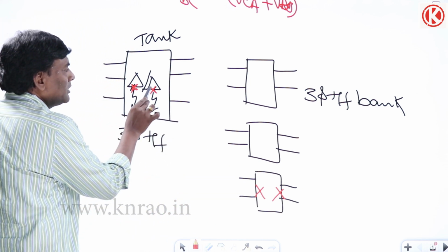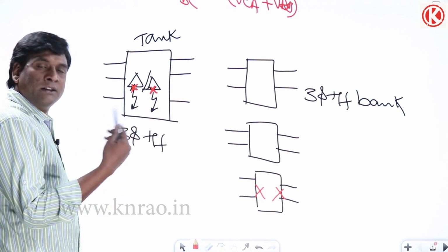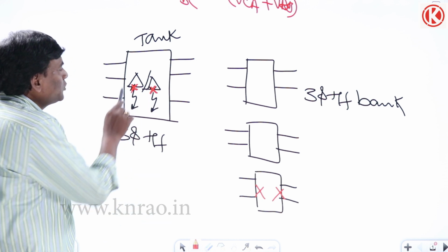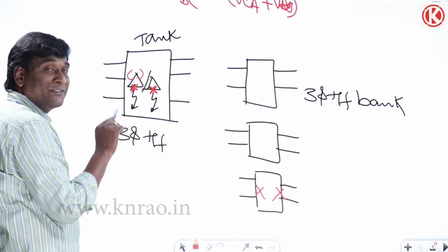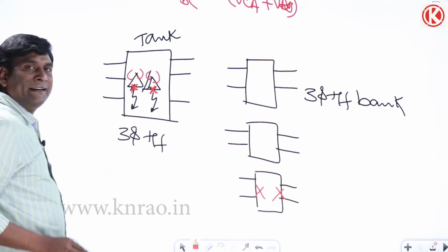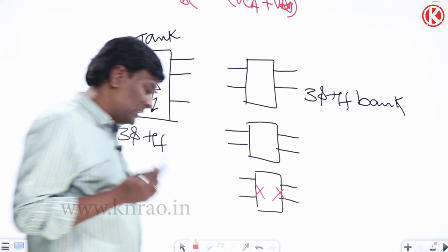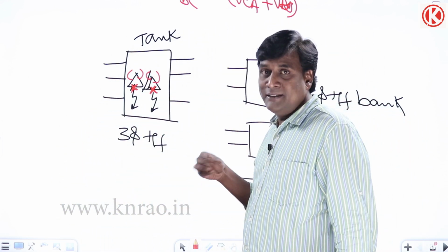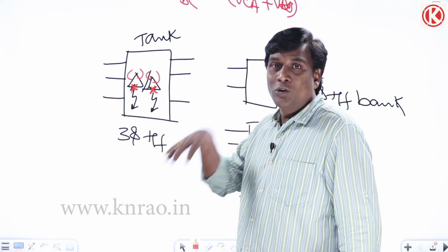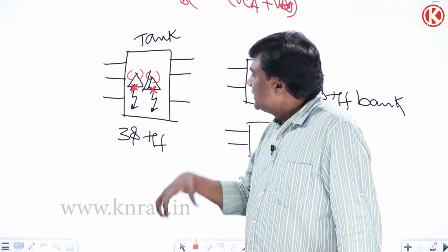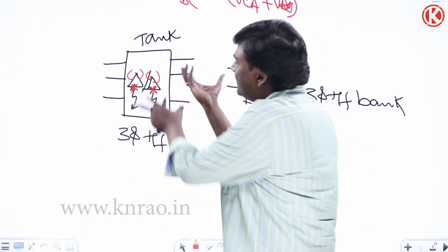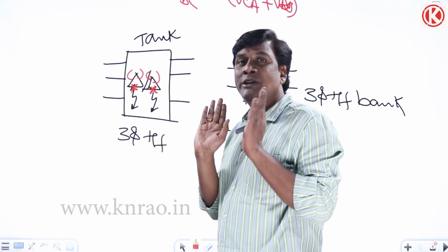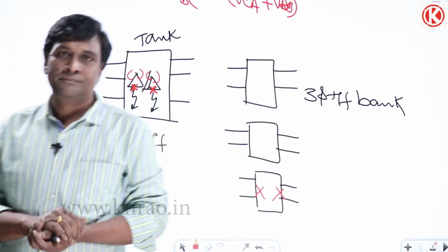The moment this particular section became faulty, the remaining two transformer phase windings can be operated in open delta connection. But in that condition, again one more new transformer delta connection should come. That particular delta should be connected here, and then the complete transformer has to go for replacement.